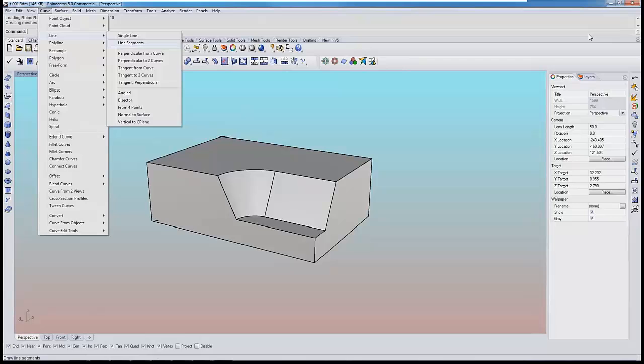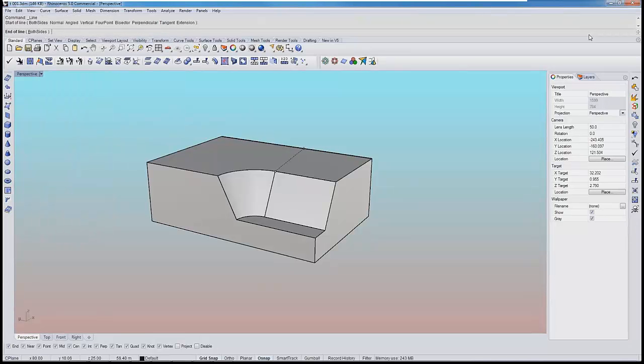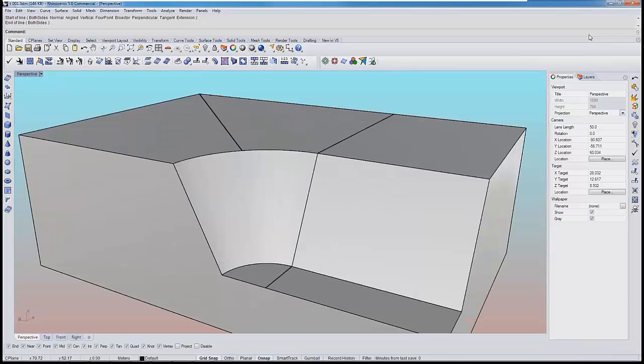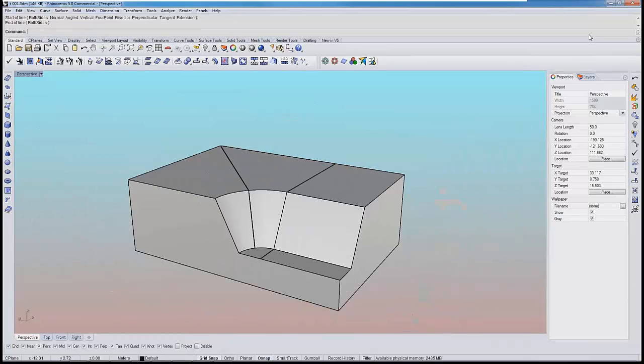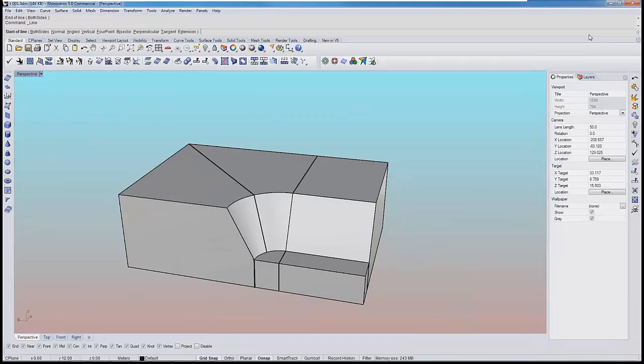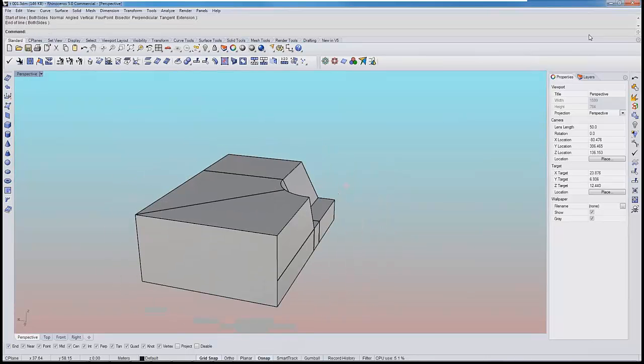Here we want to control the grid distribution. So we will go about this by subdividing this solid into a number of smaller solids. Here I am drawing a number of lines that will enable me to split these surfaces, the surfaces that define this solid, into smaller surfaces that define smaller blocks, so as to produce a number of smaller solids which would then later on be meshed into separate mesh blocks.